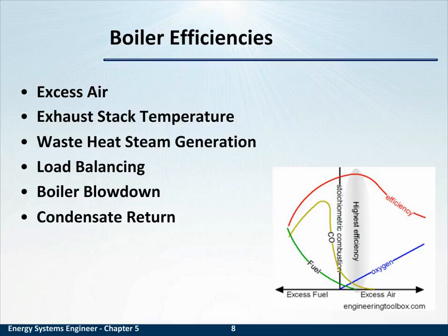As one considers the efficiency of boilers, of course, as you know, the component itself, the boiler itself, the design, the materials of construction, and so forth, have a lot to do with the efficiency of the boiler. But there are some things that, given a boiler, you can operate it more efficiently. You can maintain it as well to operate more efficiently. The first boiler efficiency item we have added here is what's called excess air.